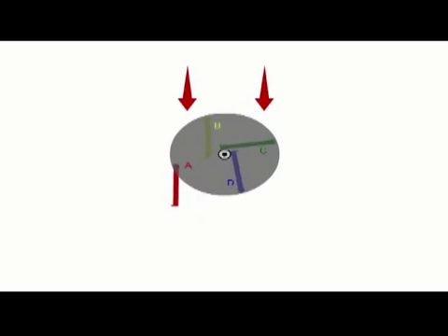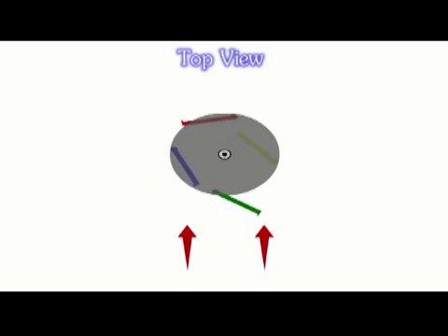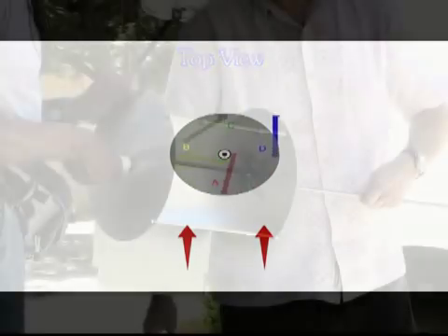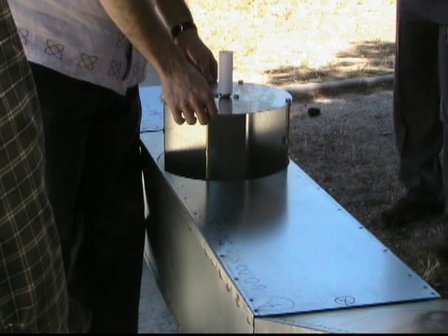When the flow of water reverses, see how the flaps flip to catch the flow on the left side of the turbine and thereby still keep the turbine spinning in the same clockwise direction, even though the flow of water in the tube has changed direction. The turbine will be mounted in the tube on a vertical shaft. After that, it's just a matter of attaching the turbine shaft to an electric generator.